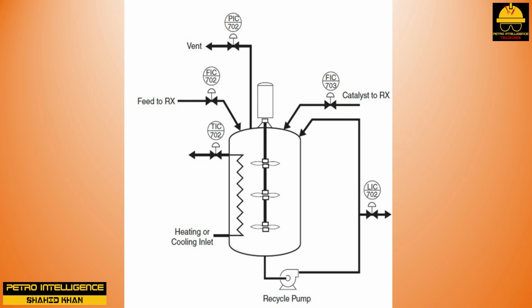Process variable alarms will be activated by analytical, composition, pressure, temperature, flow, level, and time variables. Rotational speed on the agitator may be fixed or variable. A series of interlocks, permissives, and alarms will engage during operation and will provide a support network for the technician. A series of process video trends will be displayed to track each of the critical variables.